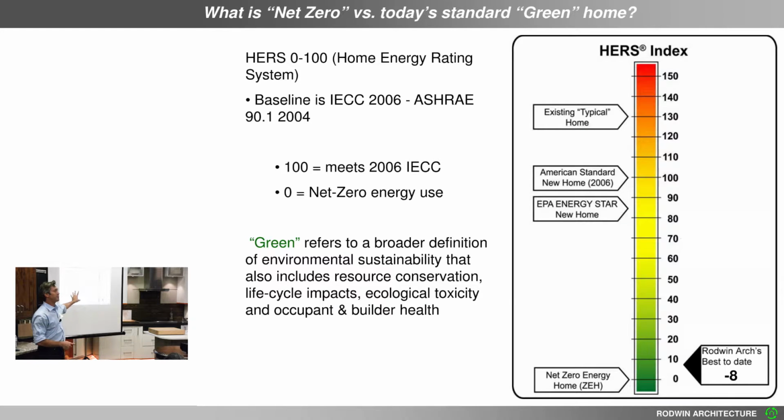This is one of the most important things for you to know because it will apply to the home tour really specifically. This is how we understand the energy efficiency of a house. This is called a HERS index or HERS rating. A HERS of 100 is the maximum amount of energy allowed by code per square foot according to the International Building Code, which is what all municipalities around the entire country use.